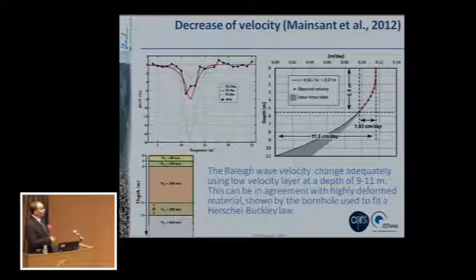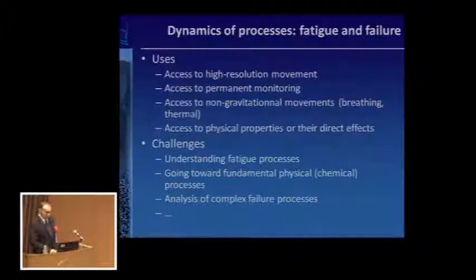And this shows that there is probably fluidization of the material. My colleague showed by simple simulation that we expect a zone that was weakened between 9 and 11 meter depths. And this is because this is the fit of a deformation profile. We have the borehole up to here. And then this part was really deformed. And we can expect that the deformation plus water fluidized the material.